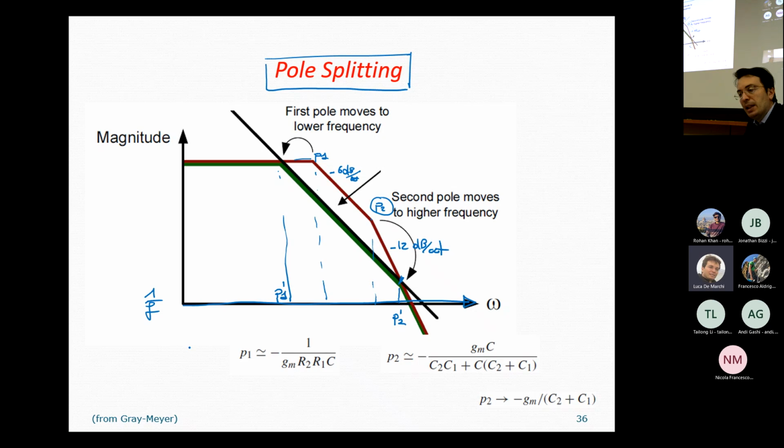Let me consider the fact that the VGS of transistor 5 is also equal to the VGS of transistor 7, because, again, due to the short circuit which are in place. Therefore, with the same principles that we have used before, we can conclude that the overdrive of transistor 5 is equal to the overdrive of transistor 7.